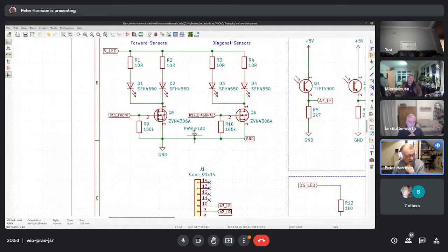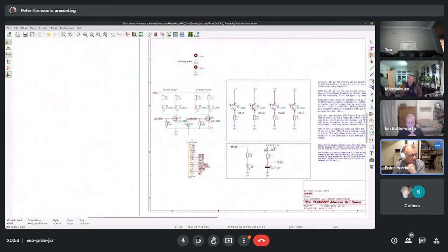Without the power flags, it doesn't know that these wires are power traces, and if you've got a component that has a net class of power, it has to know which wires are giving it power. It's a strange thing. Eagle has a similar thing, but doesn't require you to actually mark a part as a power flag.